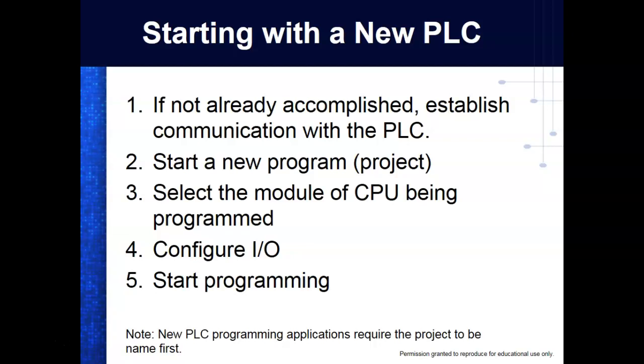So number one, we have different methods we can communicate with these PLCs. We got MicroLogix 1000. These are fixed PLCs. I think I passed that around for you in a little briefcase. And then the 1100 is what I call a hybrid PLC. It's a fixed PLC, but it can be expanded.